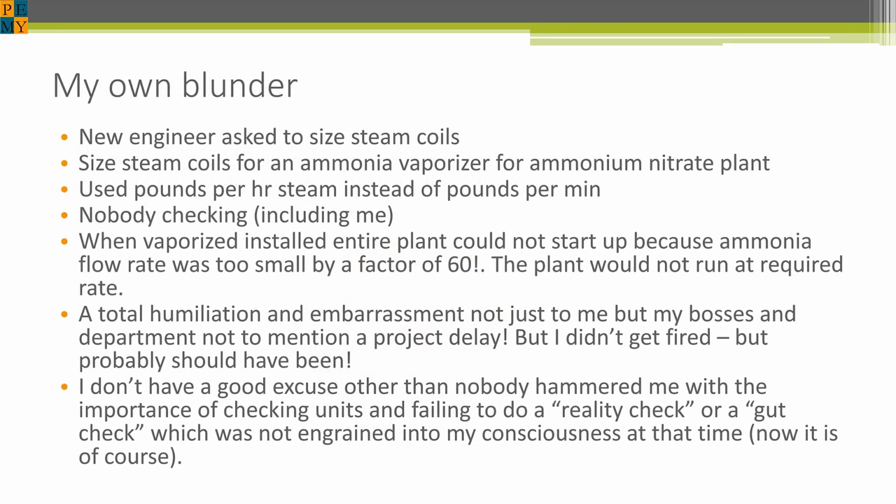Just to reinforce this point, I want to give you my own experience. I was a new engineer sizing steam coils for a vaporizer in a liquid ammonia process that was used for making ammonium nitrate. I used pounds per hour instead of pounds per minute. Nobody was checking. I wasn't rechecking my work. When the system was installed, the entire plant was running at a small fraction of what it was supposed to be running.